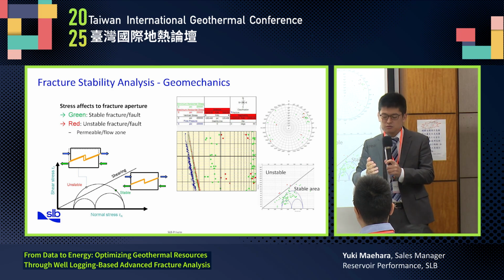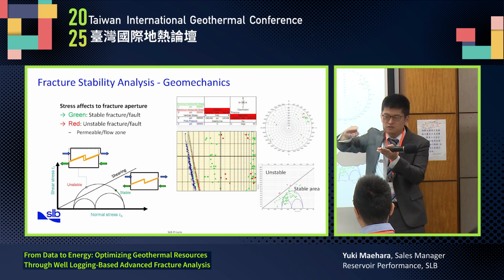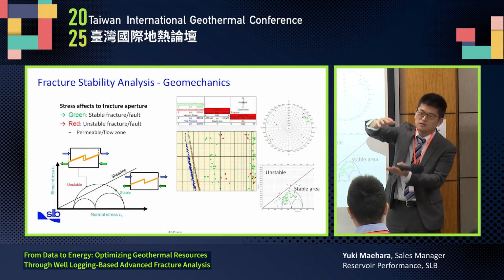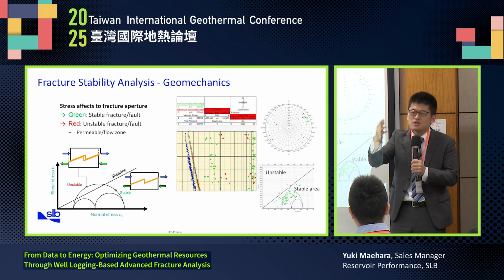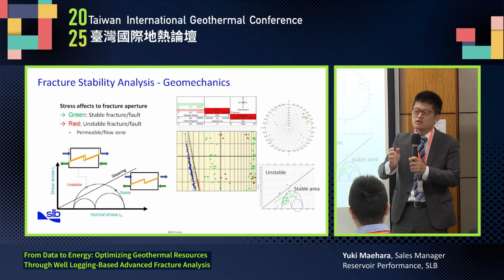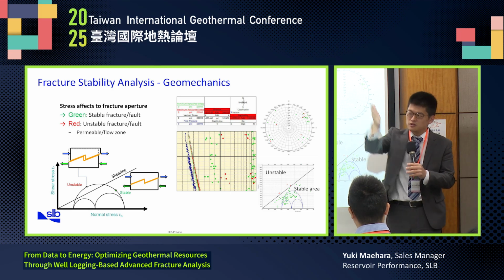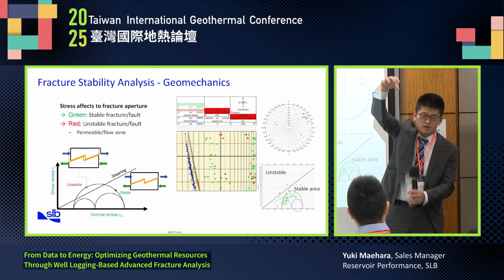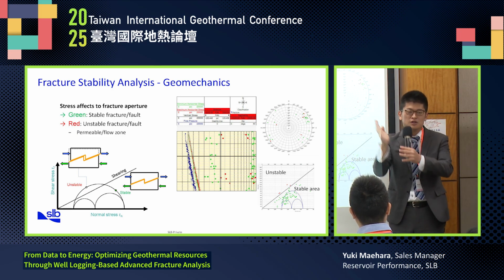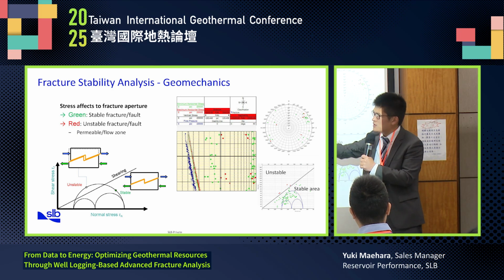So you can imagine that you have a fracture path, and then you press vertical. This fracture is there, but it's stable, right? It doesn't move. But if your fracture is a steep line like this, if you push vertically, this fracture can slip, right? Which we call unstable.